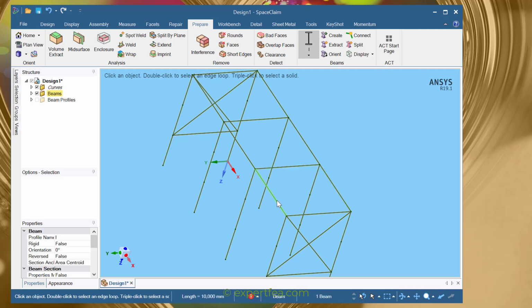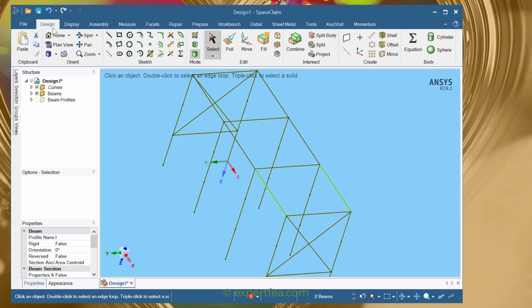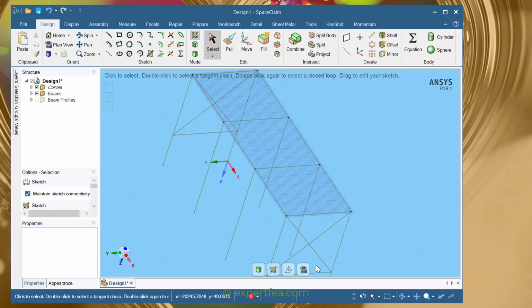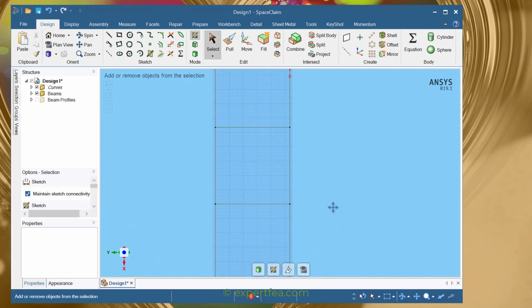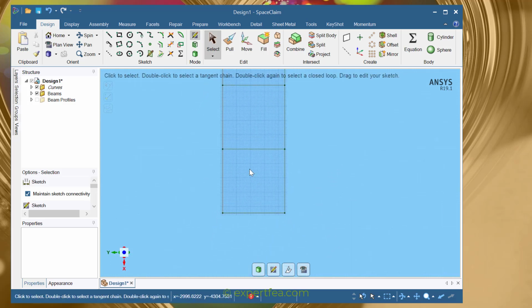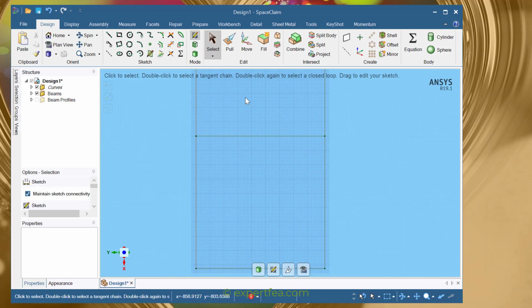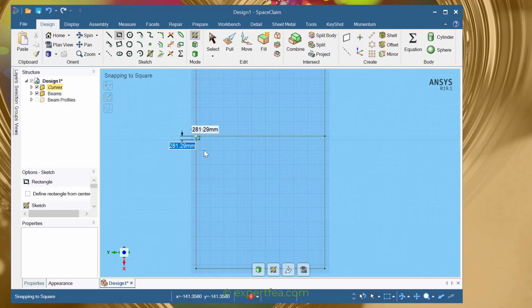If we select two lines, we can somehow position ourselves into a sketch view. So we selected these two lines and we have here a sketch mode, yes? Let's go to plane view. What I need is to create like a slab or a floor for this first portion. Let's click the rectangle and we will make sure that we snap exactly what we did here. Escape.